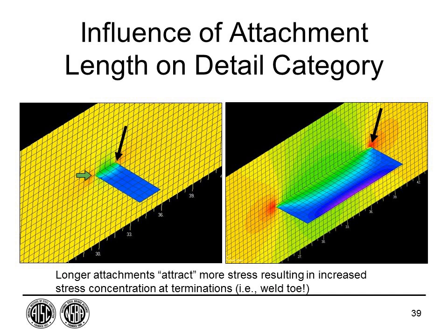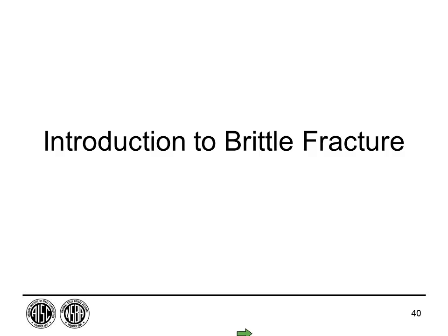And so as we look at fatigue details, the length of the attachment is what's important, and the terminations of the attachment. Along the length, the stress just flows pretty smooth. But at the ends, what has to happen, either on this end or this end? Well, it has to come in, so there's kind of turbulence, if you think of it like water, flows smoothly, and then has to come out. And so our stress concentrations often are at the ends of details or terminations of details. So that's kind of a very quick review of fatigue before we get into the specifications.